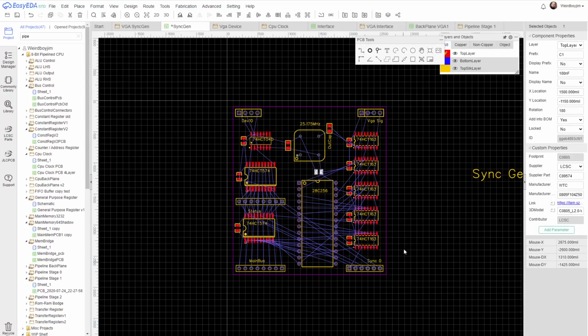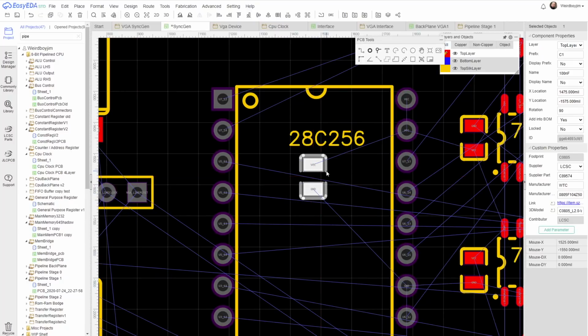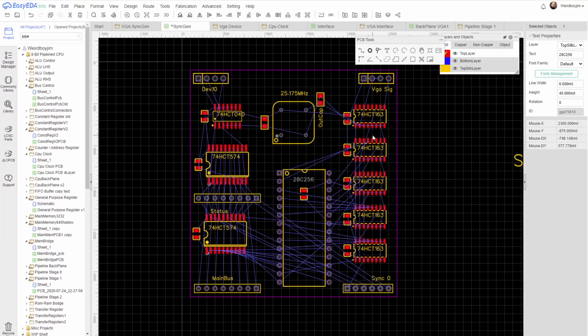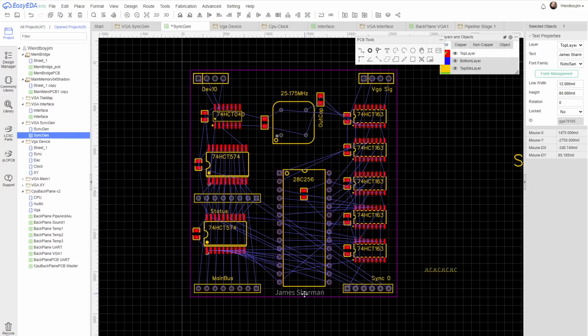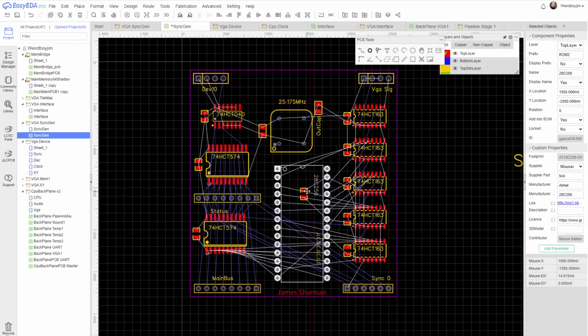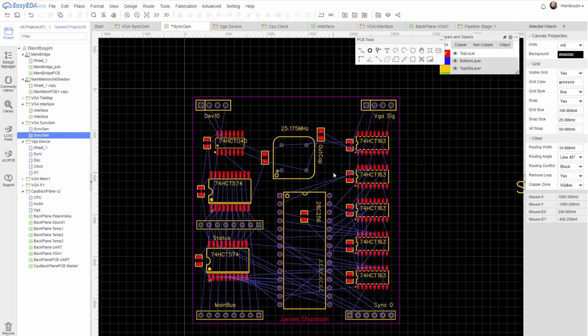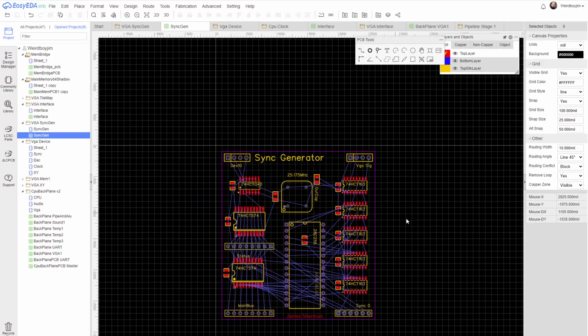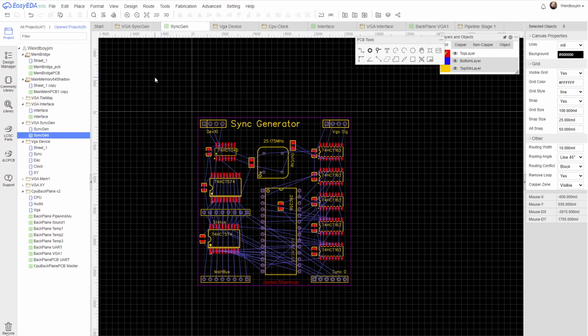It's a pretty reasonable layout though. Right, I'm going to socket this, so I'm going to put the capacitor in a slightly more central location. Okay, I think this is pretty good. I think it's going to be fairly cost effective to make this 4 layers, which is going to make life an awful lot easier for us.